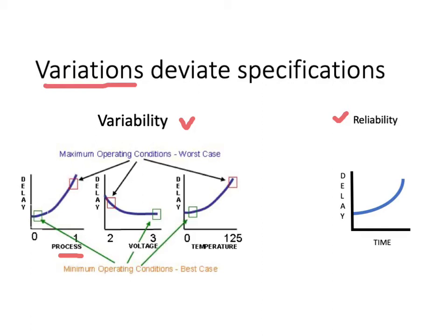So bear in mind, these are exactly the same design circuits, exactly the same transistors according to the front-end IC design, but because of the variability introduced by the process, these very same circuits will actually end up having a spread of delays. So you will have best case circuits that actually have a minimum delay, and worst case circuits that actually have a maximum delay.